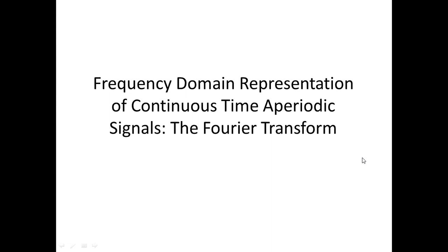Now, what is the difference, by the way? Actually, your Laplace transform had S equal to sigma plus j omega. There is something related to the real part, the imaginary part, and then there is a damping indicator, the sigma. But when we are talking about the Fourier transform, we will assume that it is always stable. So there is no question of a sigma coming in as in the Laplace. That is why we will simply represent S by j omega without considering the sigma part of it.